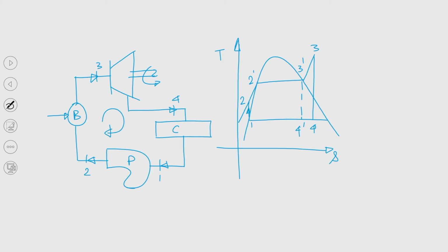See, here we are trying to increase efficiency. Again, if I try to write, our objective should be to increase efficiency. This is the efficiency of the ideal Carnot cycle, and we have studied this cycle only to analyze the performance of all real cycles against the ideal Carnot cycle. So, now according to the Carnot efficiency, if we can reduce this TL,